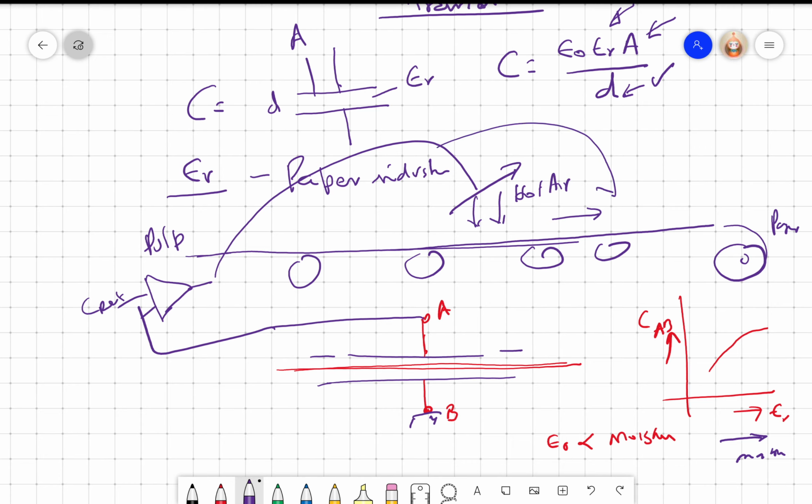So this is normally a multivariable control, speed and the temperature of the hot air, both are adjusted so that you get a moisture free paper which you can roll and sell without bothering whether the paper would deteriorate or not. The paper would not deteriorate. Okay.